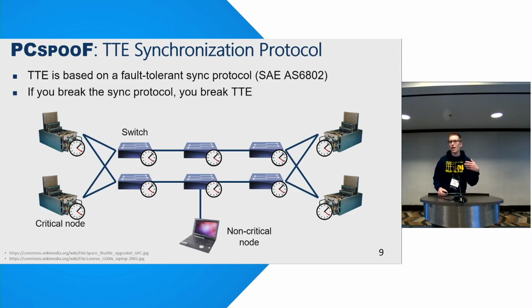The thing that makes this sort of attack even remotely possible, and in particular allows us to disrupt devices which are spread all throughout the network, is that we go after the TTE synchronization protocol. As the name time-triggered Ethernet would suggest, a TTE network only works if all of the devices are synchronized to each other. So if an attacker can somehow disrupt that synchronization, they can disrupt the critical traffic flows that rely on that synchronization to exist.